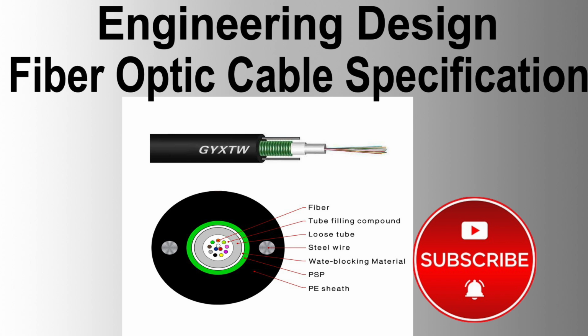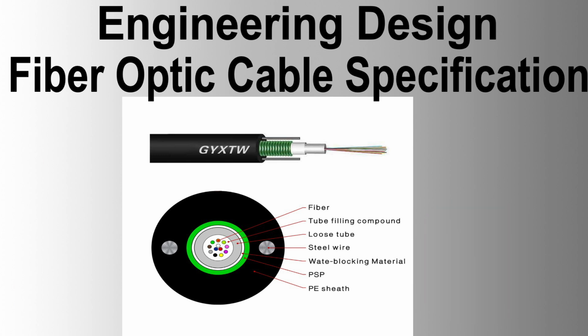Optical test and fusion splicing equipment. One automatic fiber optic fusion splicer, OTDR, and light source or power meter test set shall be provided as defined herein. OTDR shall be utilized for pre-installation and installation work. All such optical equipment shall be in fully operable condition without defects and shall be calibrated as defined by the manufacturer's recommendations.